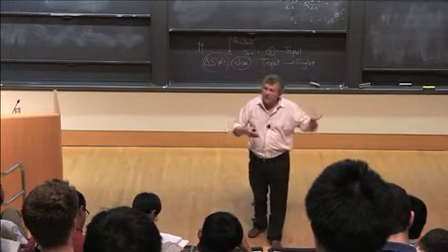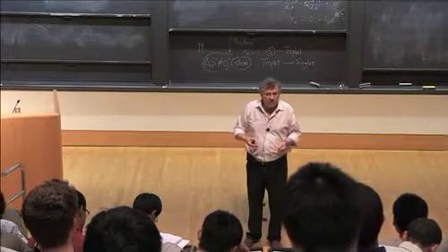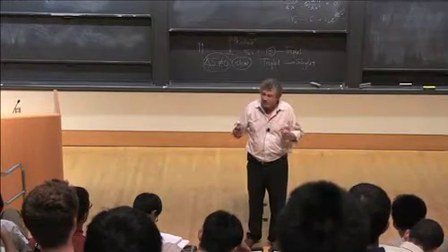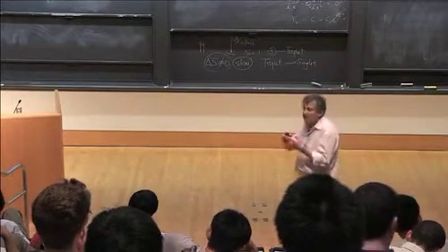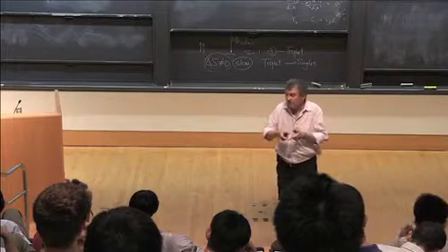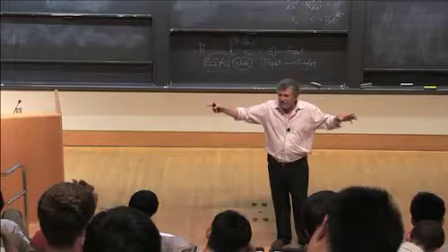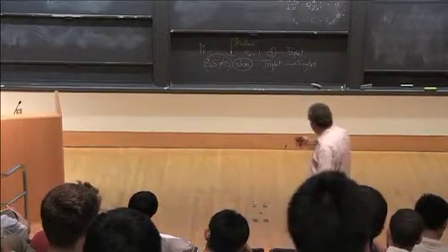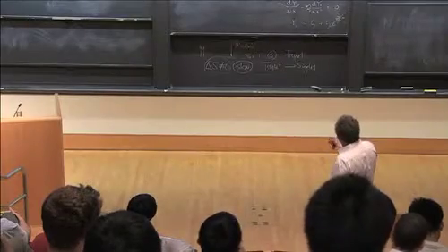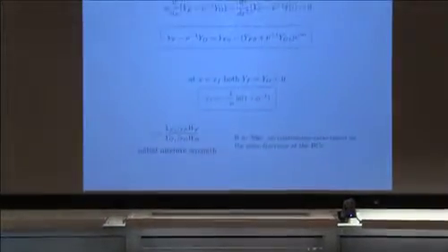If phi is less than 1, that means that you have supplied less fuel than what is needed for the stoichiometric condition. But you see, the reason it's a bit confusing is that when the fuel and oxidizer are completely consumed, they are supplied at stoichiometry, but this is at the reaction sheet, not in the initial condition, not in the boundary condition, okay? So that's why the word initial here is important. So now we obtain the location of the sheet.